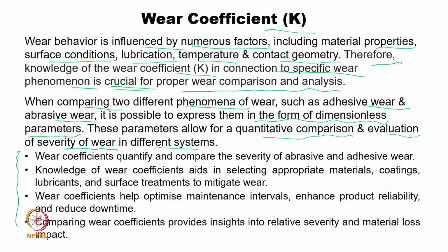What do we say? The first: wear coefficient quantifies and compares the severity of abrasive and adhesive wear. We are just writing the two wear mechanisms here, but in future lectures we will be covering more and more types of wear mechanism. We can compare wear coefficient for those also.